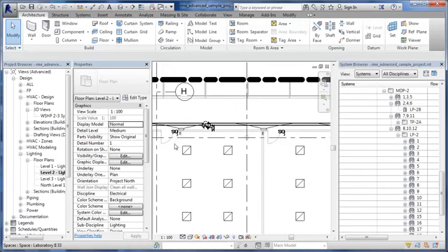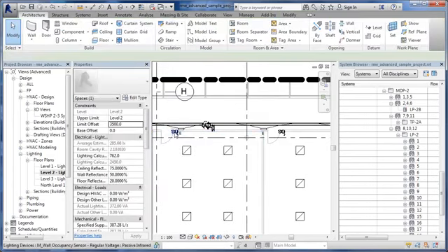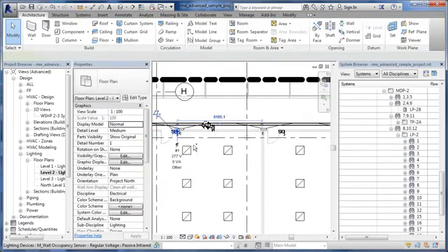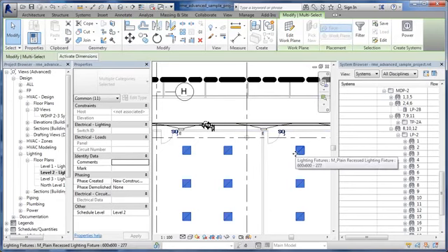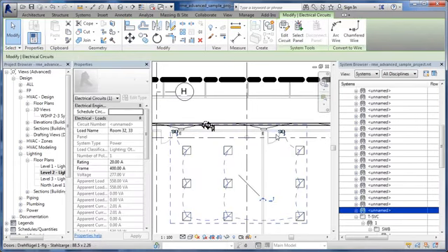So to add them back in, all you have to do is go back in here, which is kind of the other half of the example, using my control button, just like everything else. You pick the components, and then you pick the equipment and the devices. Once you have them all selected, as long as they're all able to be created into a circuit and none of them are part of an existing circuit, you'll have your power button, and that's what creates the network. From there, you can make the wires, 2 different wire styles, or not.